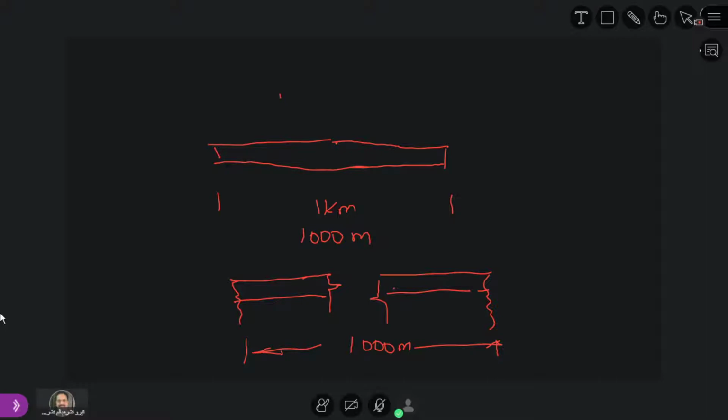Do you understand what I'm trying to say here? Since this is the same size, I break it. So that's why we use this line. This is the break line, something you must have seen somewhere. Whenever you try to draw very big objects of the same size and shape, we normally use this one.